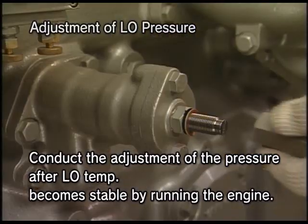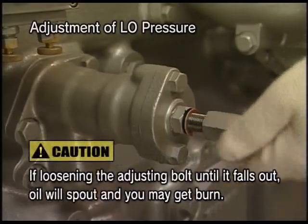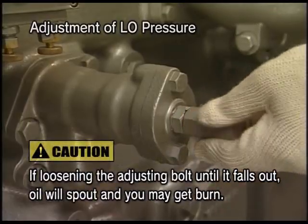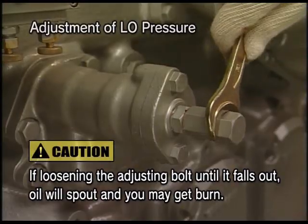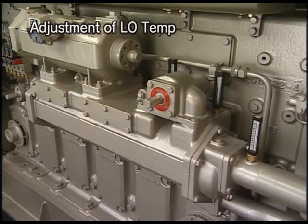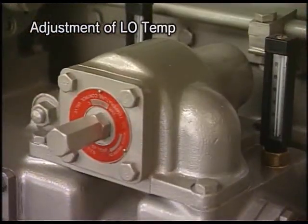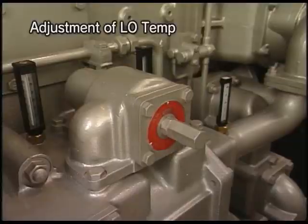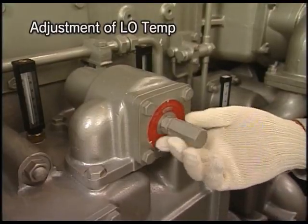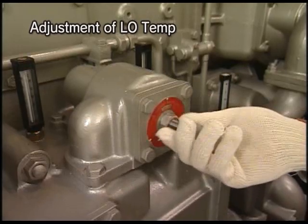After the adjustments, securely tighten the lock nut, screw the cap nut, and the work will be completed. I will continue to explain the procedure for operating lube oil temperature adjustment valve. Remove the cap nut, measure the position of the adjusting bolt, and check the valve.